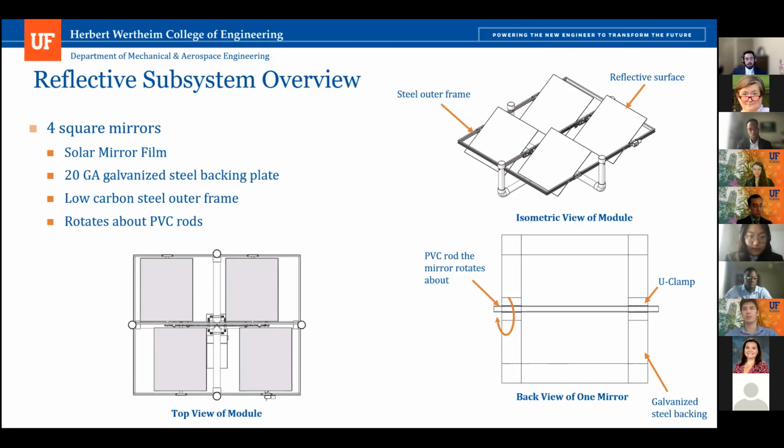Okay. And then how are they attached? They're welded together, spot welded. Okay. And then have you ever welded galvanized steel? As long as you use abrasive to remove the zinc coating in the spots where the galvanization is, it should be fine. Okay, and you've considered that in your manufacturing costs, presumably? Yes. Okay.